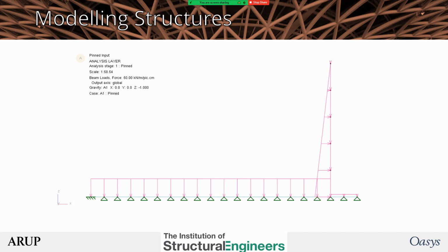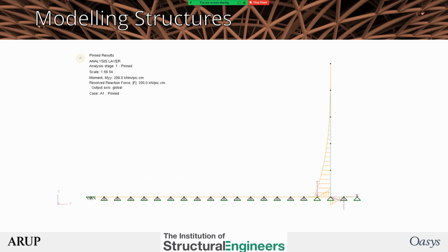Now, our building structures often have similar problems. At university, we tend to study statically determinate structures, so pin supports are fine. If a footing moves, it makes very little difference to the structure. But when we have an indeterminate structure, a multi-span beam, a frame, a raft, then suddenly the support stiffness becomes crucial and you can get rubbish results like I'm showing here. Interestingly enough, this was a reproduction of a mistake that I did make myself many years ago.